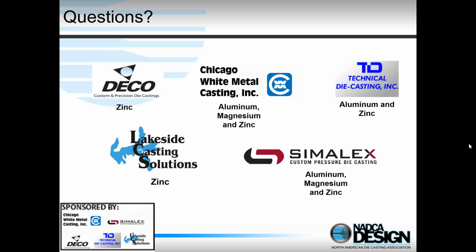Secondly, welding conventional die castings is a problem. This goes back to the porosity we talked about. We have entrapped gases in there. And when we weld it, you get a heat affected zone. This is an area that gets heated to very high temperatures, and we tend to get blistering of that part. So with a conventional die casting, no, you cannot weld it.